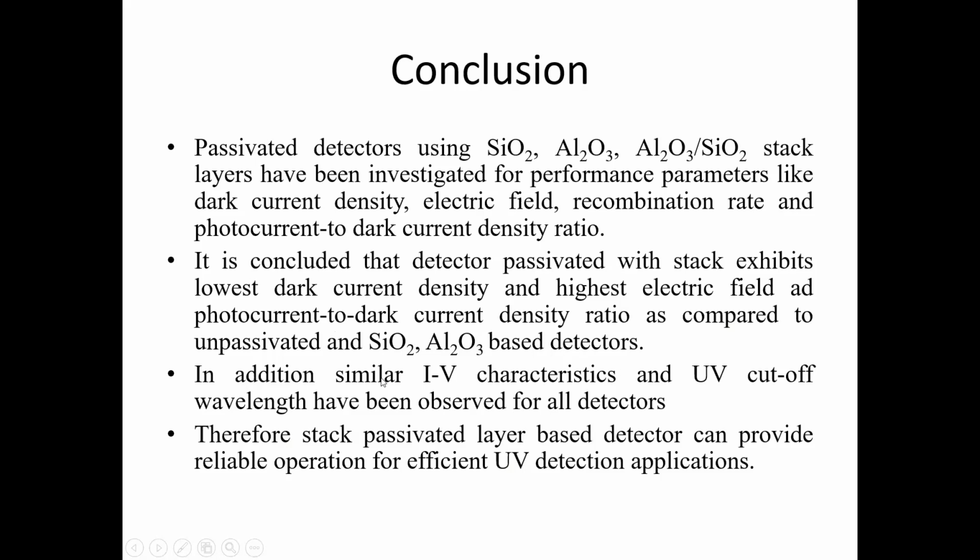In addition to these parameters, we have also analyzed that similar IV characteristics and similar UV cutoff wavelength were observed for all these detectors, meaning passivation has low effect on parameters like photocurrent and UV cutoff wavelength. After this simulation work, we can recommend that stack passivation layer based detectors provide reliable operation and highly efficient performance for UV detection applications.